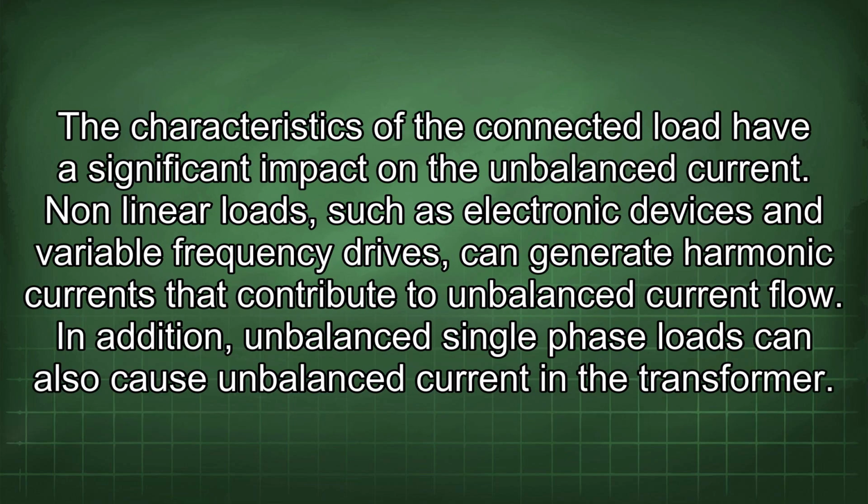The characteristics of the connected load have a significant impact on the unbalanced current. Nonlinear loads such as electronic devices and variable frequency drives can generate harmonic currents that contribute to unbalanced current flow. In addition, unbalanced single-phase loads can also cause unbalanced current in the transformer.